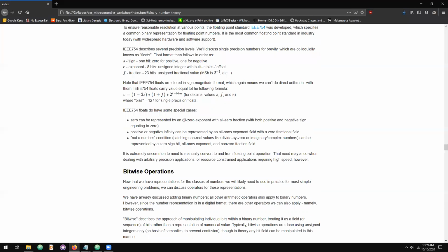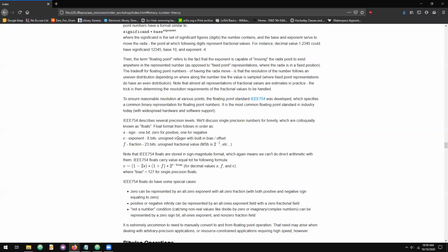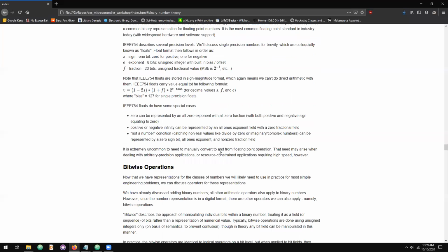But floating point is complicated, but useful for a lot of applications where you absolutely need to represent some kind of fractional value at the computer level. That's not all cases. So I would recommend, from an embedded systems engineer point of view, stick to integers for any case that you really can.